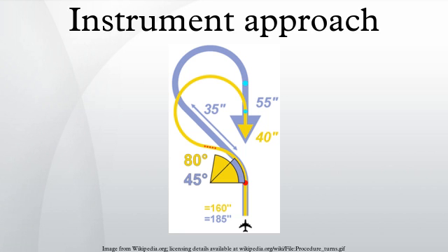Before satellite navigation was available for civilian aviation, the requirement for large land-based navigation aid facilities generally limited the use of instrument approaches to land-based runways. GNSS technology allows, at least theoretically, the creation of instrument approaches to any point on the Earth's surface. Consequently, there are nowadays examples of water aerodromes that have both land-navigation-based as well as GNSS-based approaches.